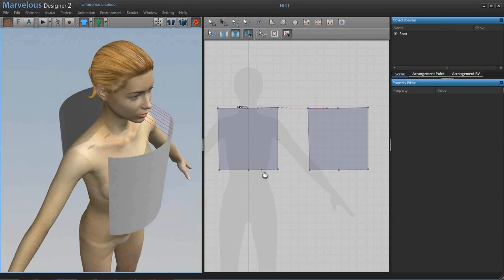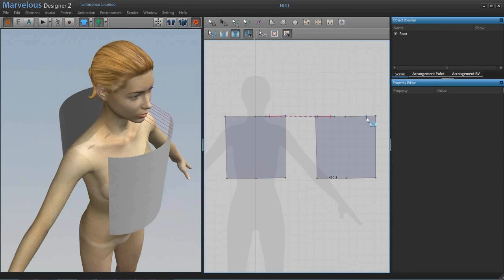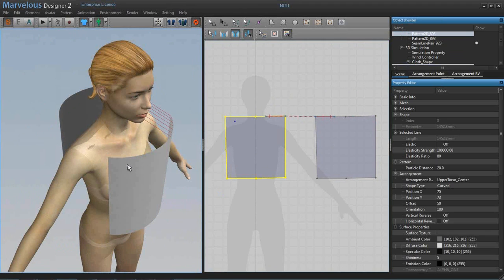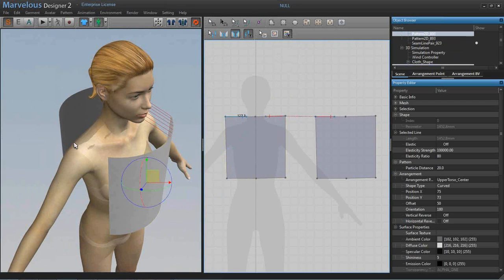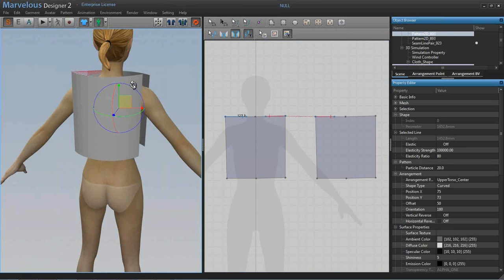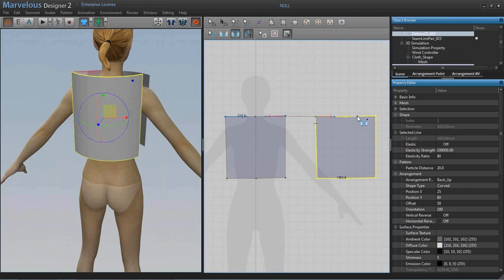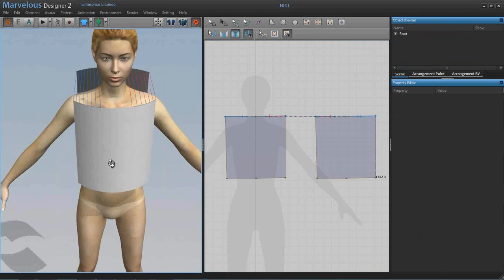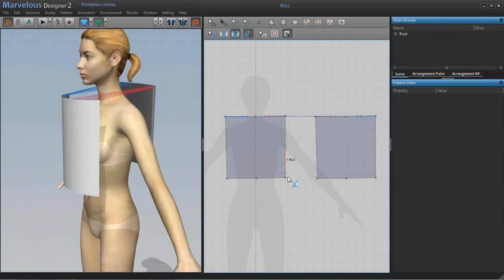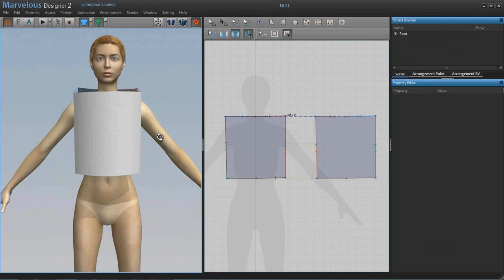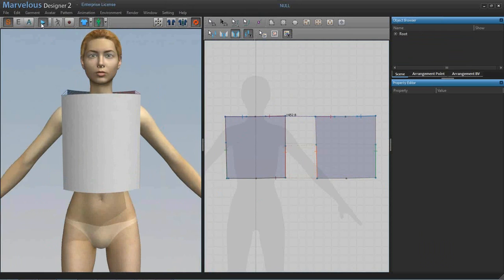Sometimes you can find it hard to tell which line should be stitched in the pattern window. In that case, you can use the glue picking point. You can find this point on the same position of a pattern. Then set a seam here, find another line and set a seam. Now I'm gonna stitch the rest of the lines of the side, like this. Okay. Then turn on the simulate button to drape this top.